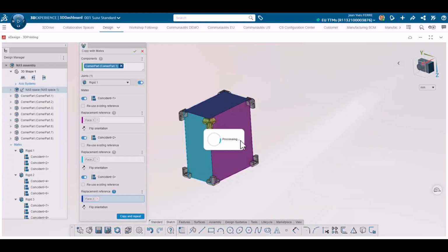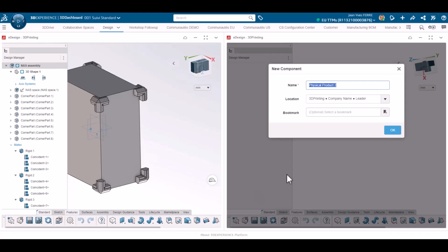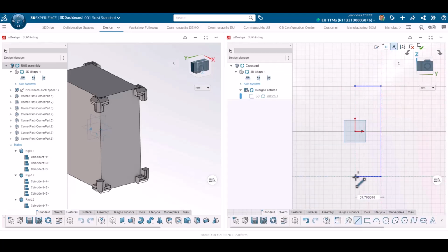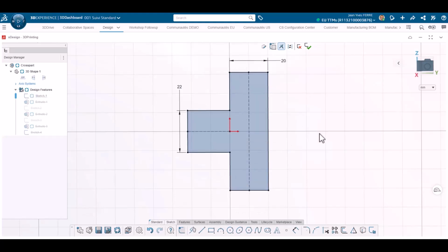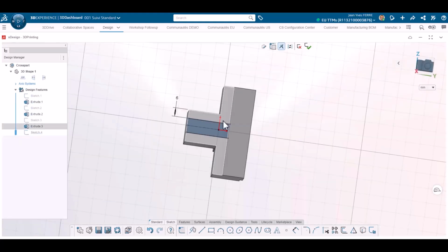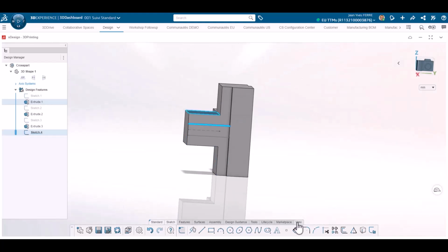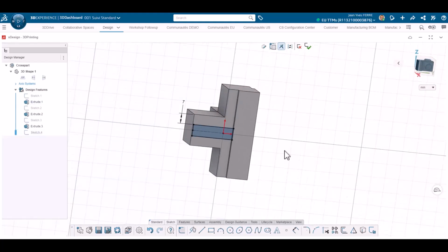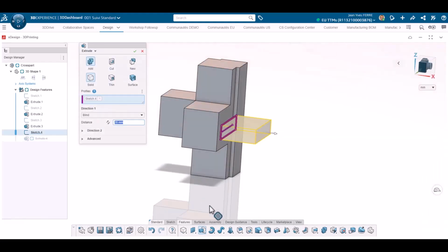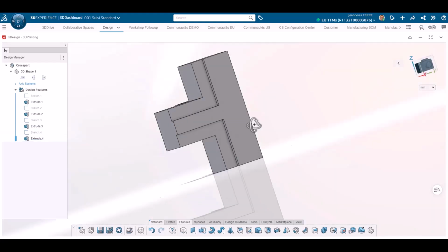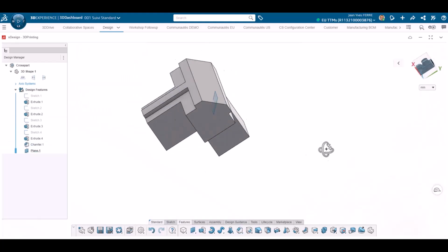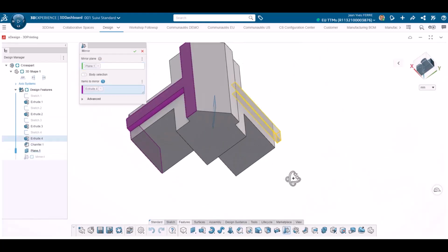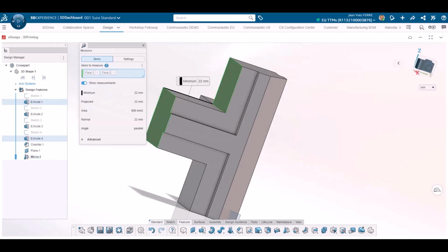Now I create a cross part in the middle of my assembly, because length of my parts are limited by my 3D printer capacity, so I cannot create only one vertical bar. This cross part will look like the corner for the recess and the chamfer, and of course I choose same dimensions for width and for nut holes. The only difference will be the bosses for long transversal parts that will add strength to the whole assembly. I choose slightly bigger dimensions to make sure these parts are really strong and won't bend.